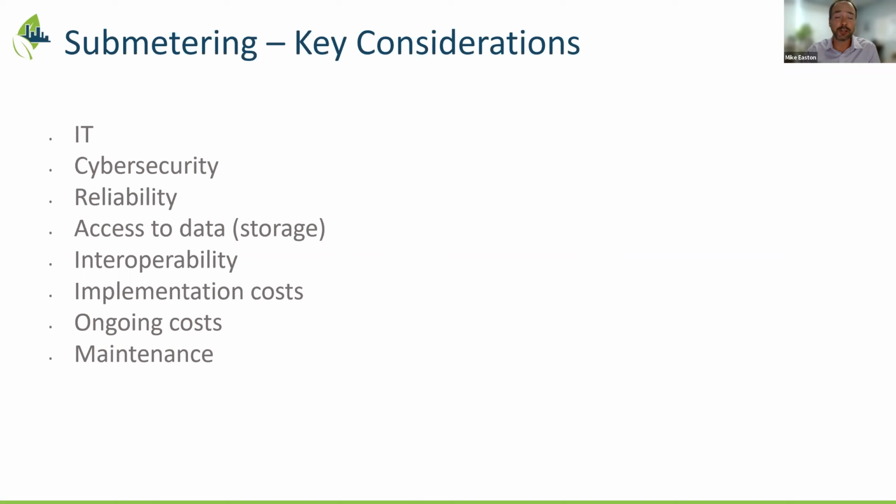So if we mentioned Measurement Canada earlier, if you've got a Measurement Canada approved meter in, say, for gas, or a utility grade meter in for water, you're probably good leaving that meter in the field for 8 to 10 years before even needing to check its accuracy, because there's so many of those deployed at a utility scale. The accuracy of those meters is very good for the long term.